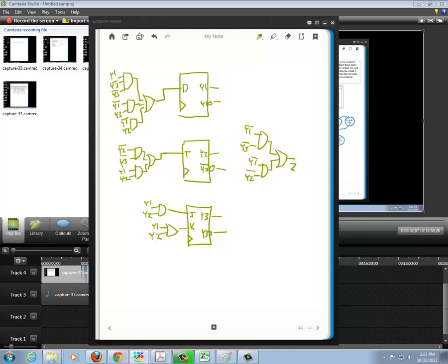And there's Z. So here again we have our finite state machines with the state variables or the state registers. We have the next state decoder logic, which is all combinatorial, and the registers are our flip-flops, which are sequential, and then we have the output decoder logic, which is also combinatorial.